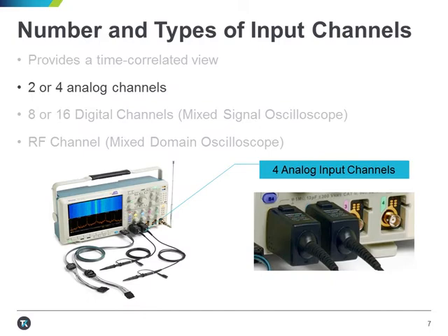Except for some very basic hobbyist entry-level scopes, most oscilloscopes have 2 or more analog channels to allow you to compare the timing of signals. The analog channels have to be designed for really good range of linearity, gain, accuracy, and flatness, and at the same time have some reasonable robustness. By that I mean mainly electrical robustness, in that they can't break every time you connect a cable after shuffling across the floor on a dry day.